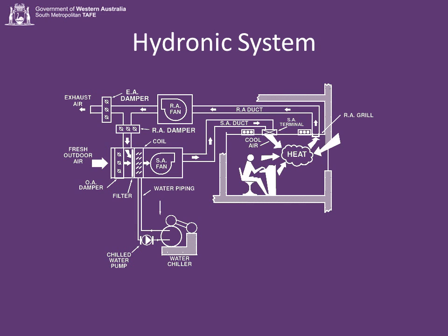We pass cold water through that radiator. We call it chilled water. Typically we're chilling the water down to about 5 or 6 degrees Celsius. And we chill the water down so that the radiator, the heat exchanger, gets cold, and then the supply air we're typically supplying at around about 12 degrees Celsius.